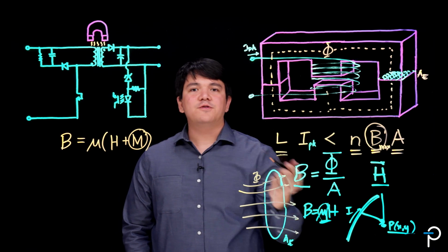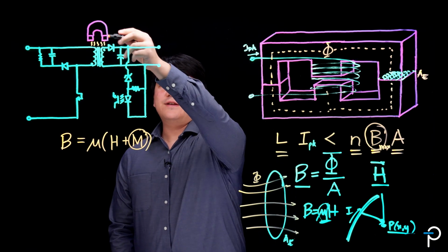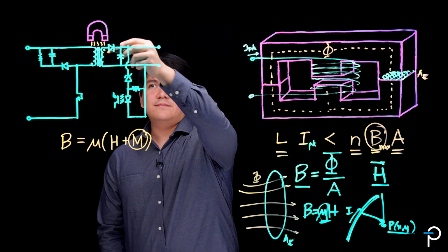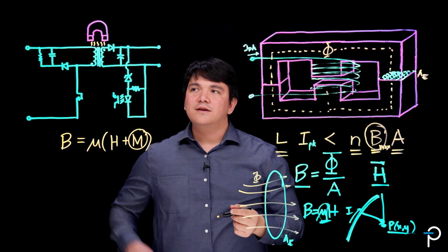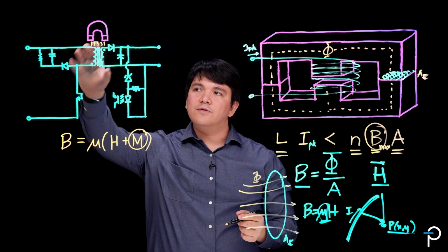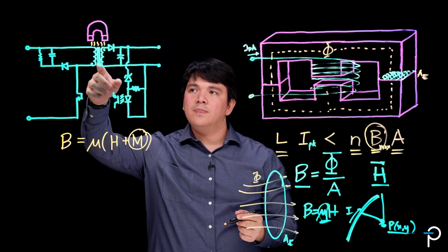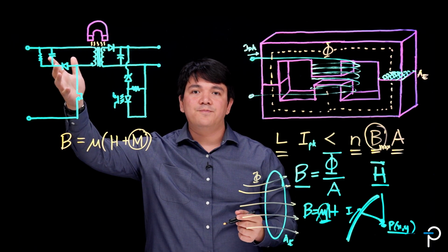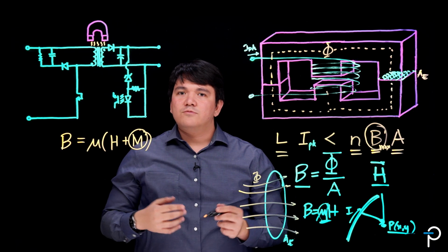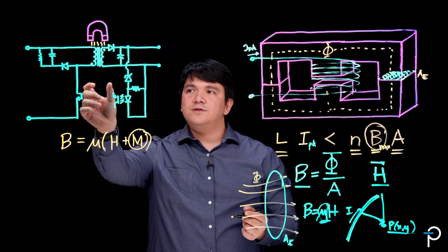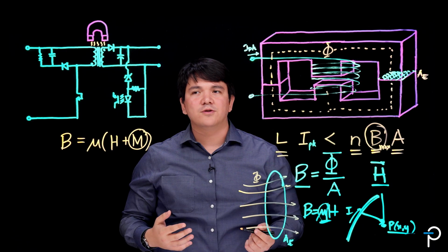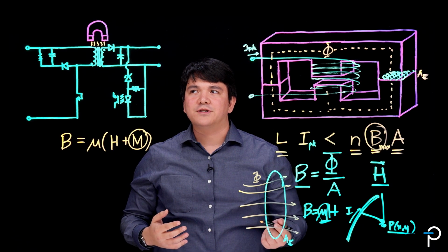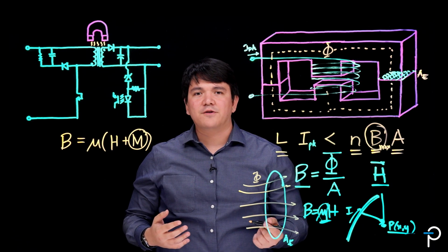And it's dependent on a few things, like the strength of the field that's caused by the magnet, its position relative to the transformer, and it's also dependent on the magnetic material of the core. Normally, we use ferrite cores because their properties are favorable for switch mode power supply operation. And ferrite cores are ferrimagnetic.